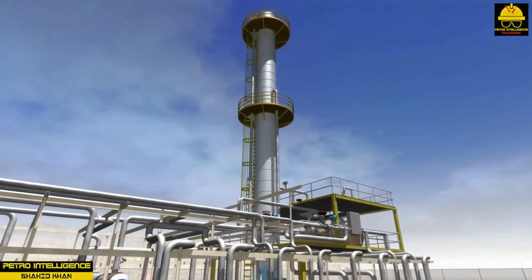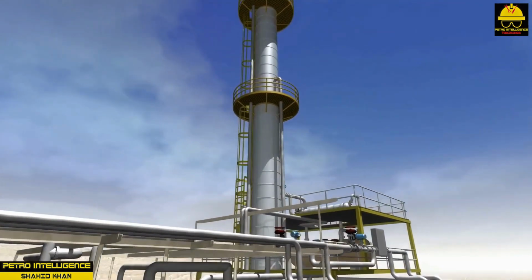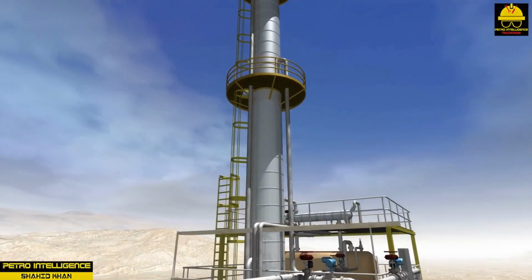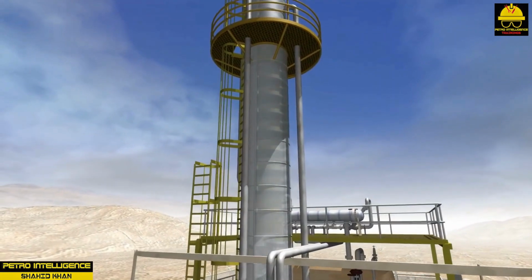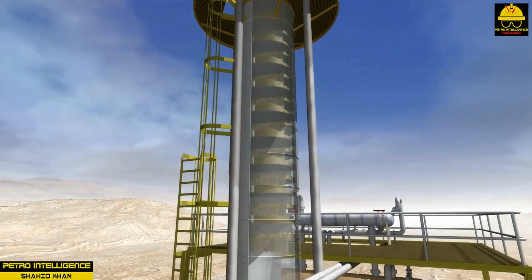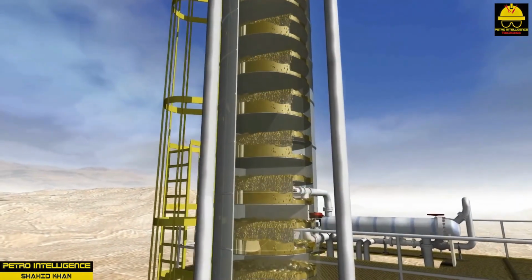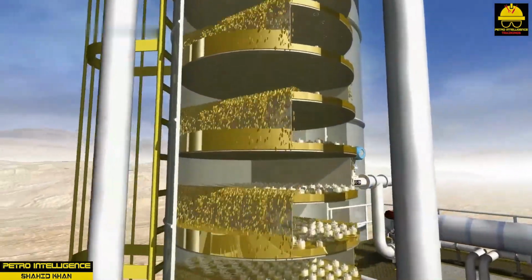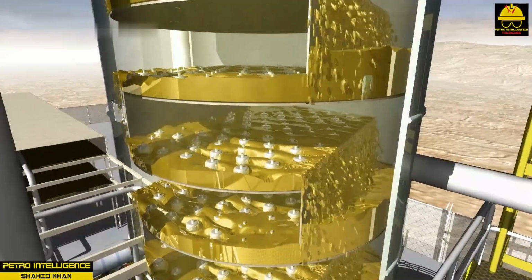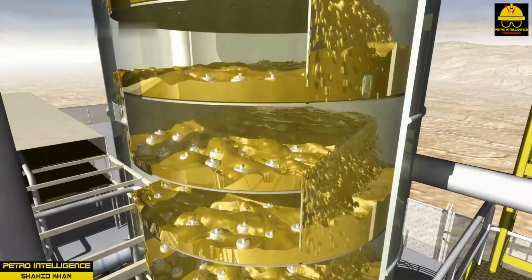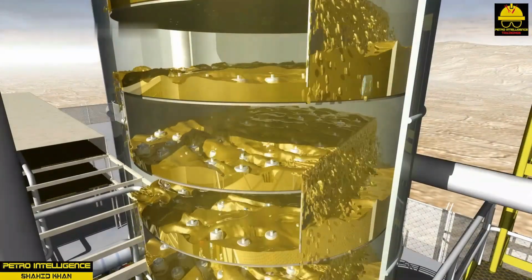The lightest component goes out the top of the tower in a vapor state and is passed over the cooling coils of a shell and tube condenser. As the hot vapor comes in contact with the coils, it condenses and is collected in the overhead accumulator. Part of this product is sent to storage while the rest is returned to the tower as reflux. A reboiler maintains the heat balance on the tower by reboiling the components that have given up some of their energy during the distillation process.